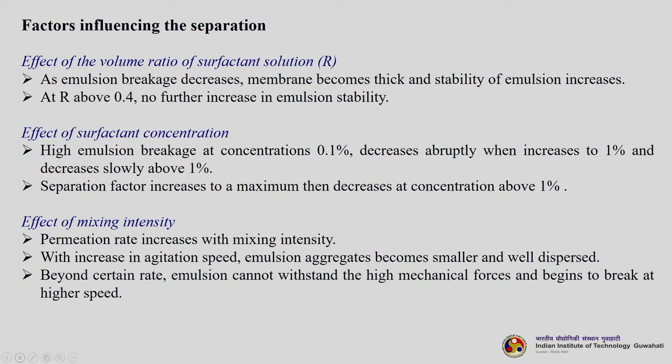Then effect of surfactant concentration: high emulsion breakage at concentration of 0.1% decreases abruptly when concentration increases up to 1% and decreases slowly above 1%. Separation factor increases to a maximum and then decreases at concentration above 1%. Effect of mixing intensity, this also plays a very important role. Permeation rate increases with increasing mixing intensity. With increase in agitation speed, emulsion aggregates become smaller and well dispersed. Beyond a certain rate, emulsion cannot withstand the high mechanical forces and begins to break at higher speed.